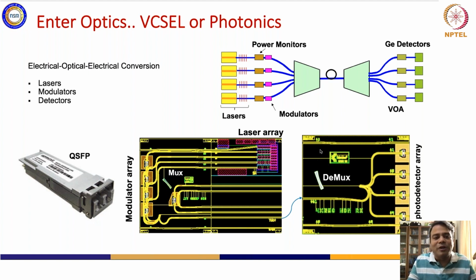How do you launch data into the optical fiber? Basically, it's nothing but a laser which is being turned on and off at the same frequency as your data rate. When the laser turns on, it sends a pulse of light, and the photo detector detects it and converts it back into an electrical signal, making it a 1. If the laser is off, it is a 0.